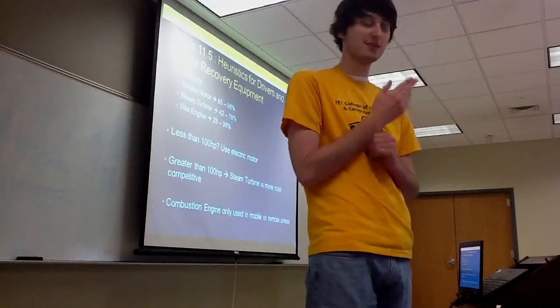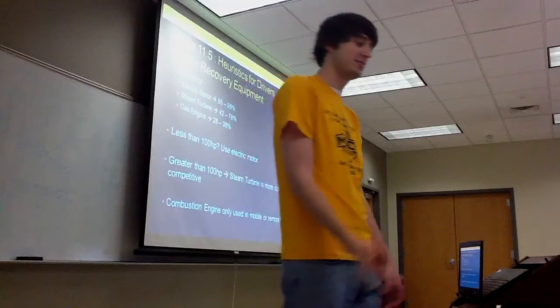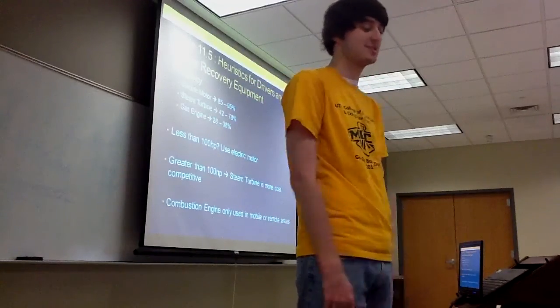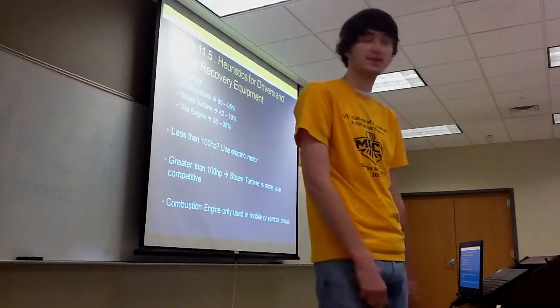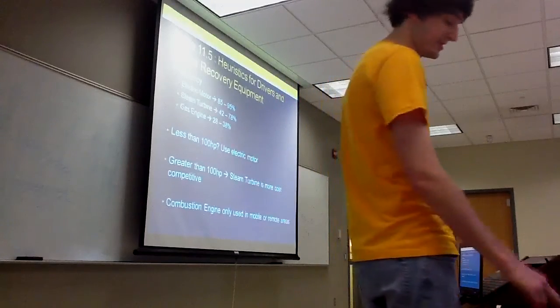So if you have an operation where you need less than 100 horsepower, the cheapest approach is to use an electric motor. But when you go above 100 horsepower, it's just an approximation that a steam turbine is usually going to be the most cost-competitive approach. And then combustion engines should only be used when you're in mobile or remote areas.